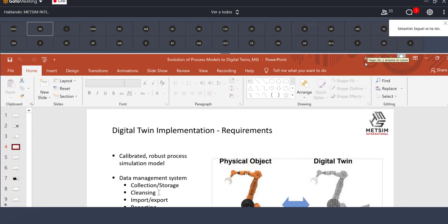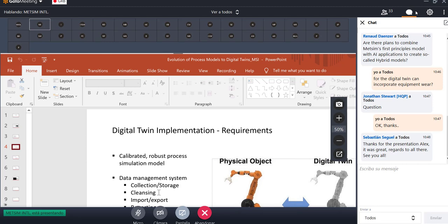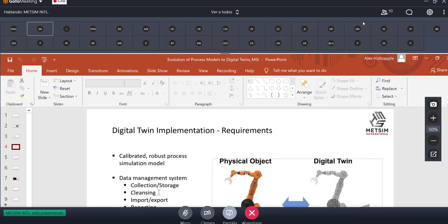Jonathan, it actually makes perfect sense. And we could do a whole other hour. I have a whole other presentation on Metsim and geometallurgy. We won't get into that now, but you can certainly contact any of us to take you through that. But what we've done within the last few years is we've created a mine module within Metsim. So we're not creating the mine plans, but what we can do is read that information in from Minesight or Vulcan or any of these other programs that are used to develop mine block models and mine plans. And we can actually create them within a Metsim process model, which then connects, just like we talked about with the discrete event simulation. The mine block model is now your dynamic input to the metallurgical plant.